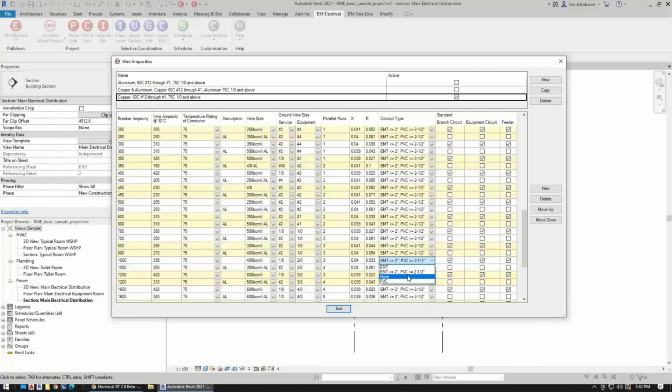And we don't have a specific conduit size because the conduit size depends a little bit on whether it's got a single pole, so it's got a single run of wire, or it's a 3-pole circuit, so it's got 3 circuits. It has a neutral, if it has a ground, and what the size of everything is. So the conduit size will vary for a specific ampacity. So we're just saying, okay, use these conduits and figure out the one that works for a 40% fill.